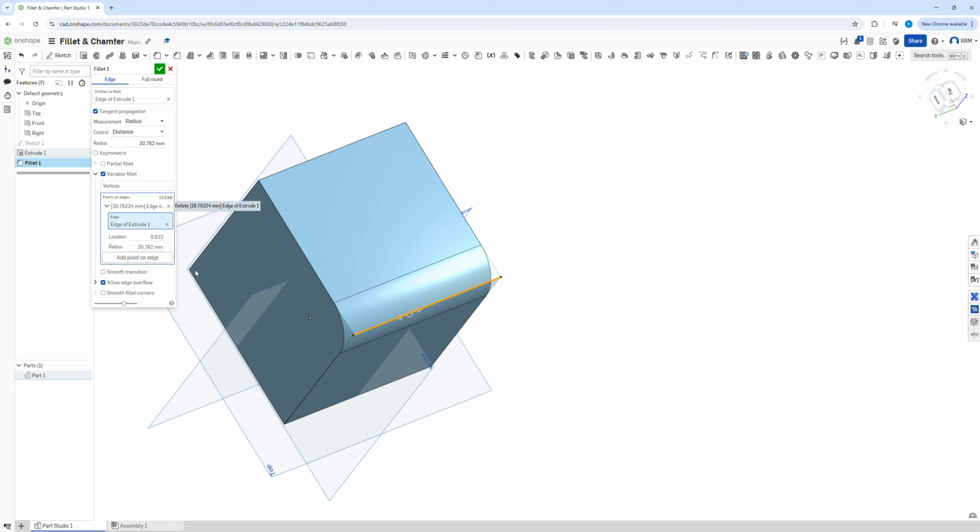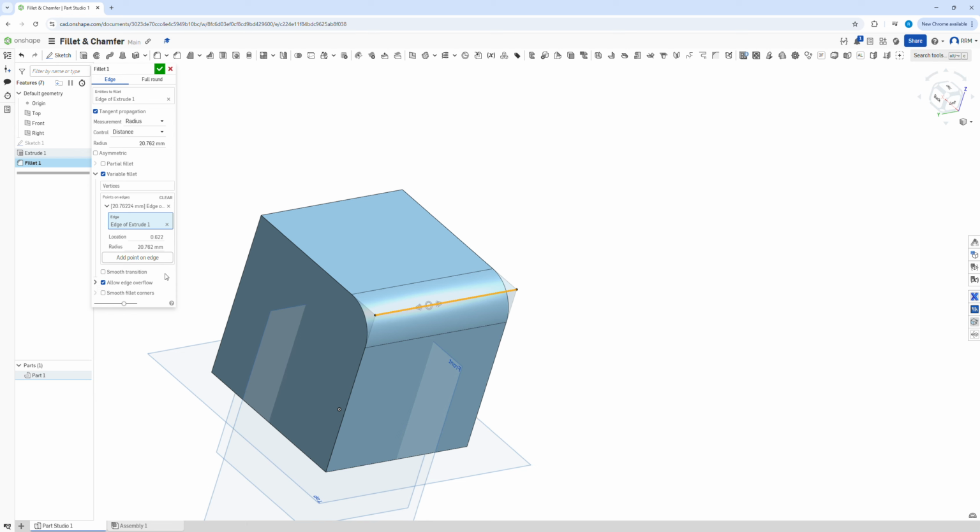And what will actually happen is when I move this around, put the point on the edge there, we can then basically change how much the radius is going to be. So we can say make that one 40. And if we go and just take this one away, back into this, you can see how that can then be moved along at a different size. Okay, so again, this would be 1, this would be 0. If we go 0.8 along, you can see how this is much wider here and much narrower back at our 20 that we originally set. Okay, so that's going to be 20, this would be 20, and this point here is going to be our 40. All right, which can be quite useful depending on what you're trying to do.